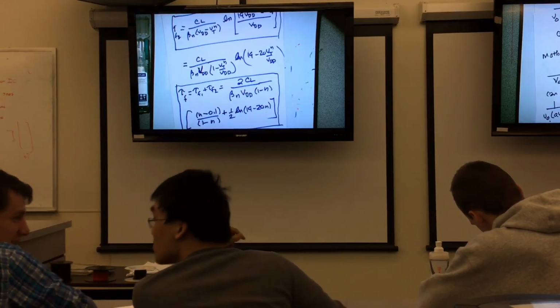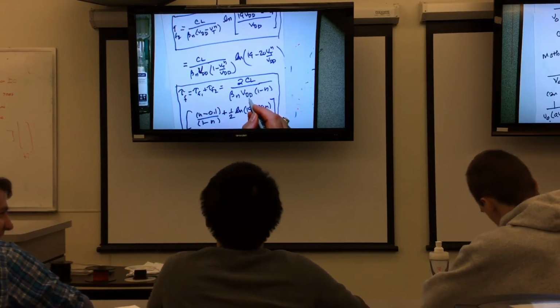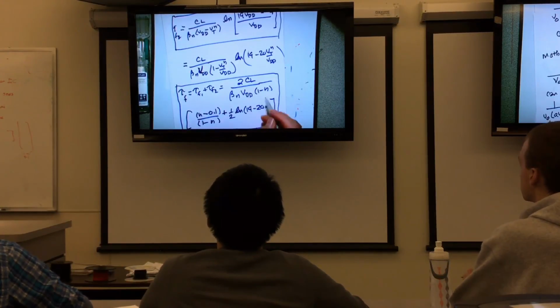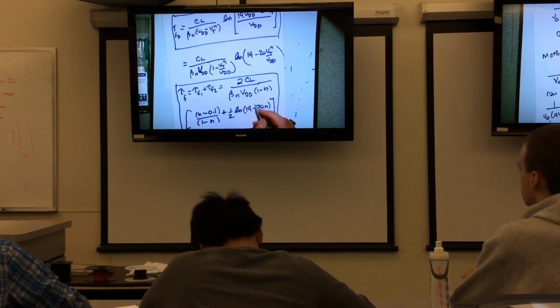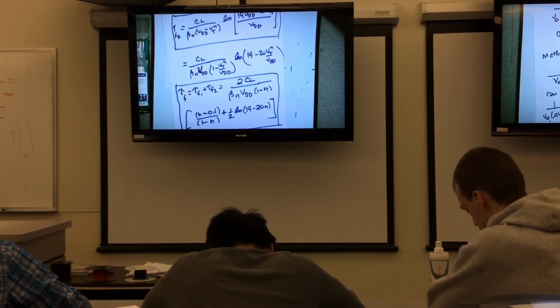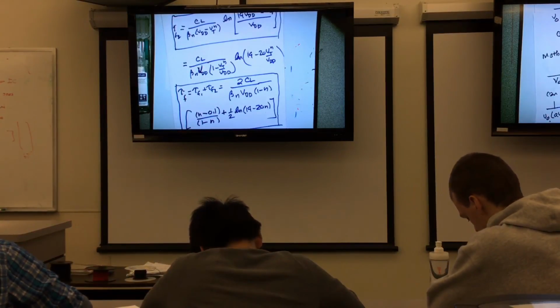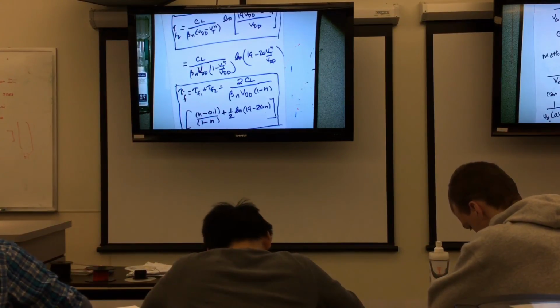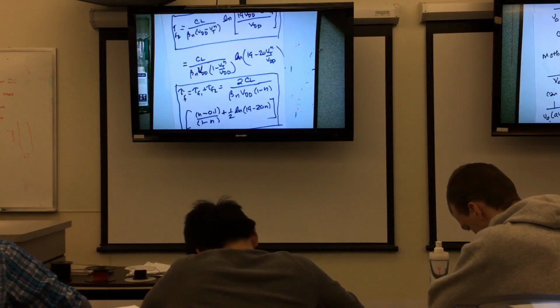And they both share this common feature that if you want to go fast, you make VDD big. Of course, if you make VDD big, the amount of energy that you're storing on those capacitors before it's all dissipated in transistors is also big. You also have problems with breakdown voltage in the oxides.